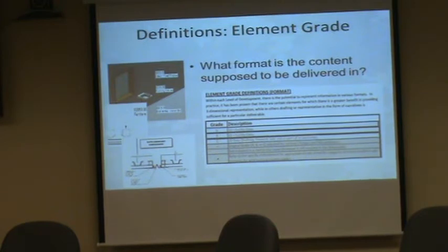There's some cases where you just don't need a 3D object, but you need the data on the object. So you stick in a 2D symbol and you stick some data on it. And 2D only is drafting, line work, text, whatever's in your drafting lines, your drafting views, that's all over there. Original grade adjusted for contract changes for field conditions is your plus, your minus is not included in the model.